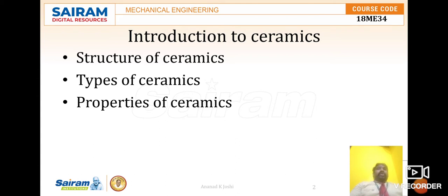The ionic bond occurs between metallic and non-metallic elements that have a large difference in their electronegativities, and ionically bonded structures tend to have rather high melting points since the bonding is strong and non-directional.